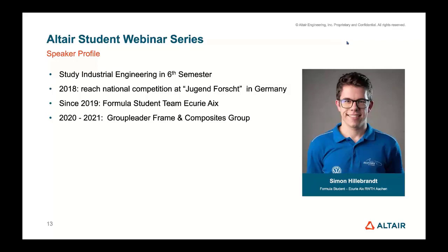I think one question was which failure criteria was used during the simulation of the composites. I'm not sure which one he used directly, but there are different failure models included in the programs that he mentioned. He mentioned ESAComp, which is a laminate pre-design simulation, where we have the Hill, Tsai-Wu and Puck and Cuntze failure criteria, and the same failure criteria can also be applied in an OptiStruct simulation.